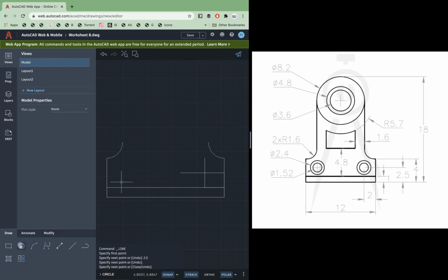Okay, now select the circle tool, and first we should know the radius of these circles. So now you can see the outer circle is showing diameter 2.4, so radius is 1.2. So we go here. Actually, you see, I cannot snap to this middle point.